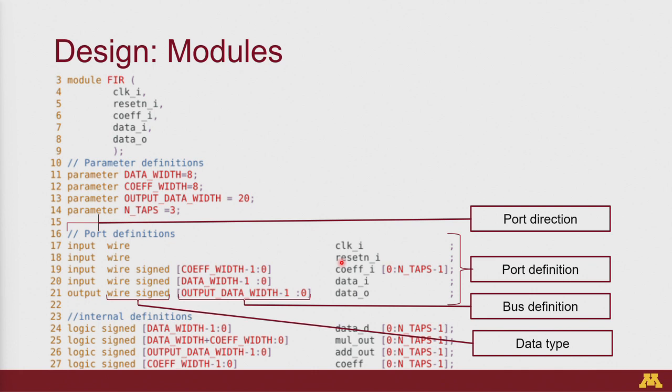Let's say for example you are considering a memory location. The packed dimension you can think of as contiguous memory in your device. The unpacked dimension is like a separate memory block altogether. So all the packed dimension indicates is that you're defining your variable in a contiguous memory kind of way, or you're defining it as a bus which is meant to interact as a whole.